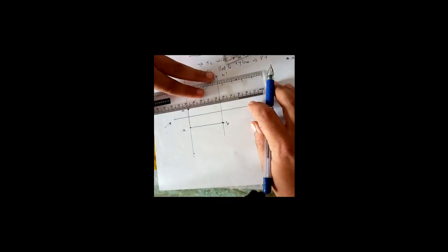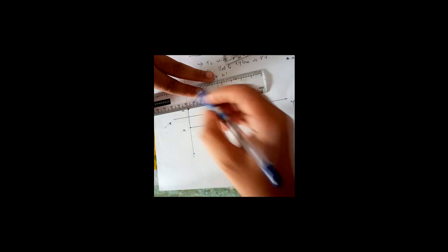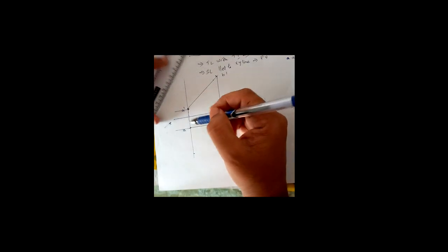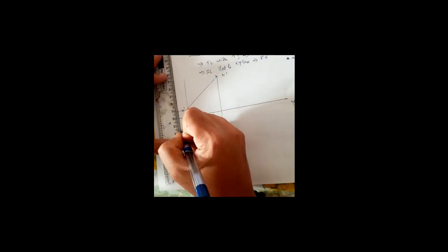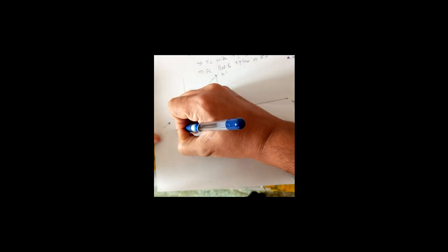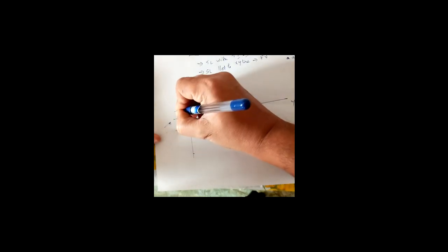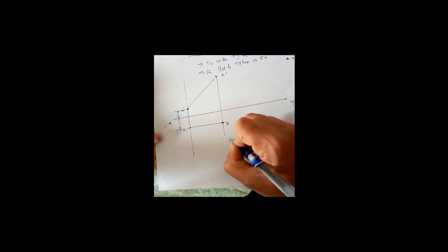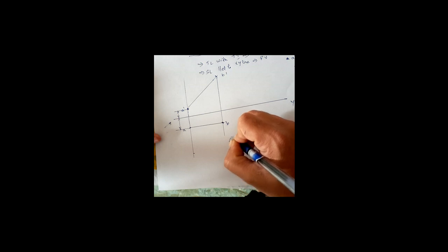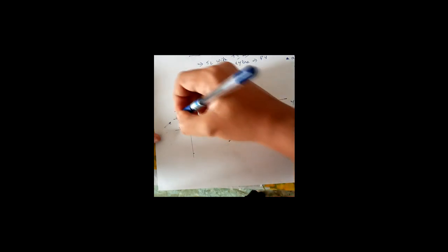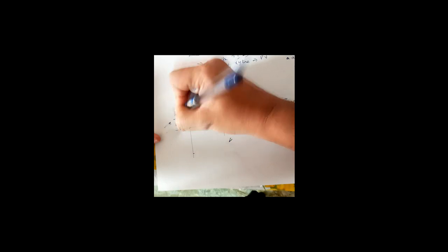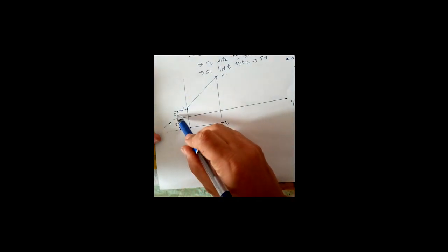Now for dimensioning, see it's very important how to dimension it. So draw a light line from A dash, draw a light line from point A, and also draw a light line across this, see, light line. Now draw arrowhead, that should also be a light arrowhead. Always arrowhead should be like this only, that is very small angle, some 15 to 20 degree, and there should be a good length to this arrow. And here now you have to dimension, this is 15 and this is 10. It should not touch here, see, it should not touch, it should be above 10.